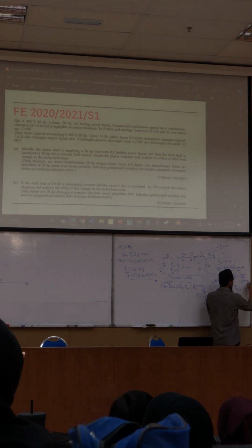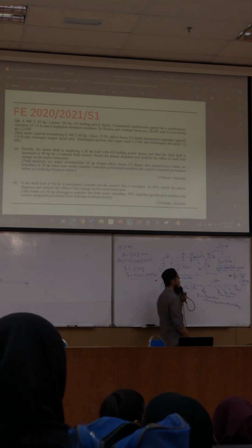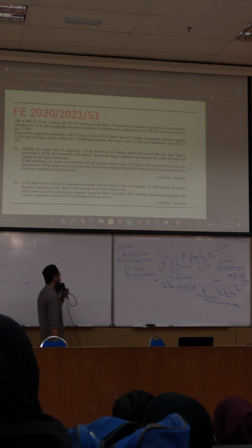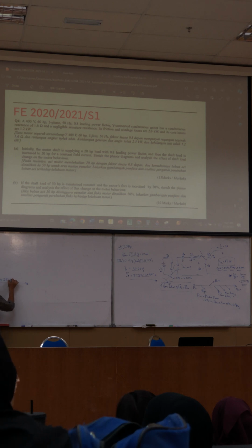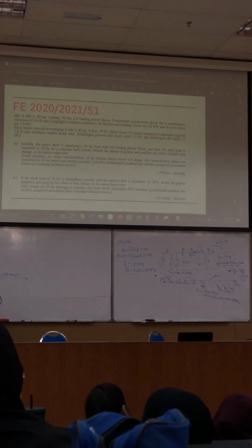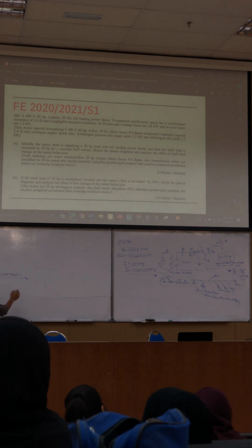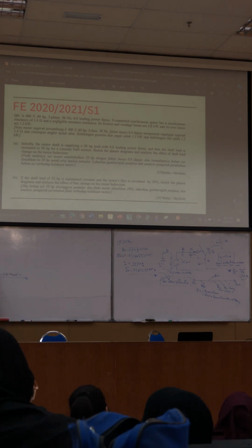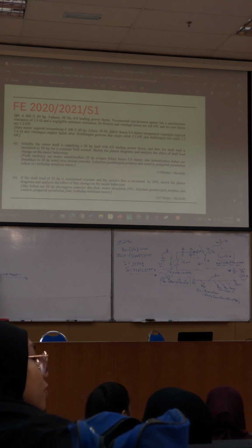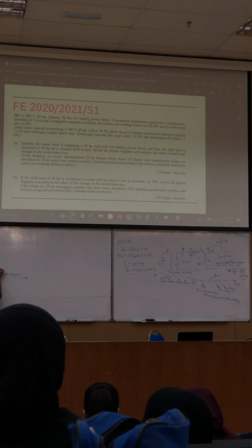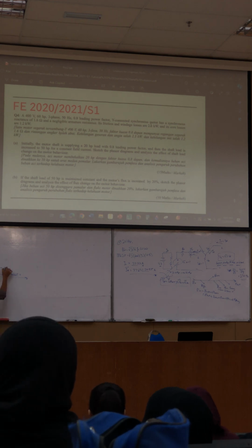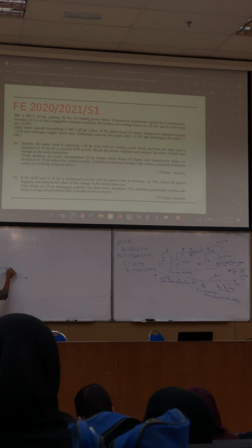230.94. So this is your V phase. So you can sketch your diagram already. Angle 0 degree volt. This is your V phase. And you have your I phase, which is, let's say here, theta. So I phase is 33.23 with angle 36.87 degree ampere.